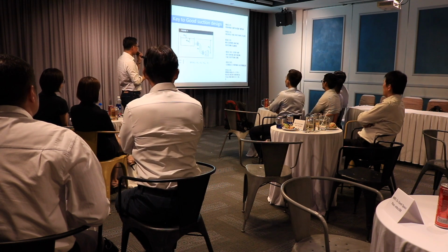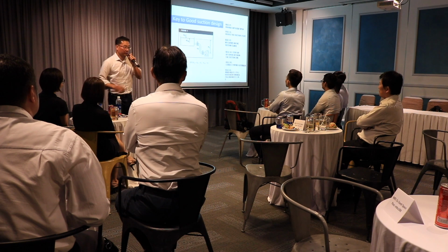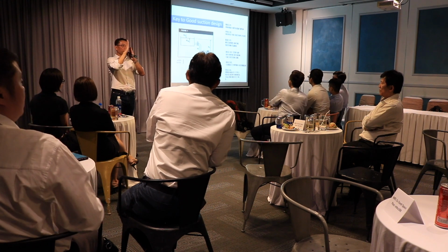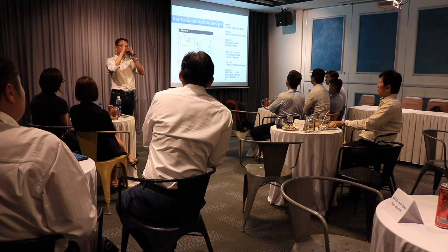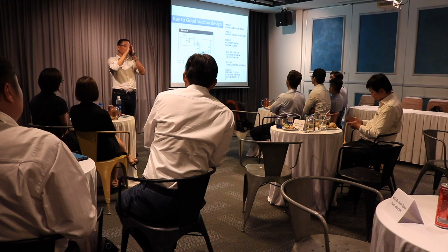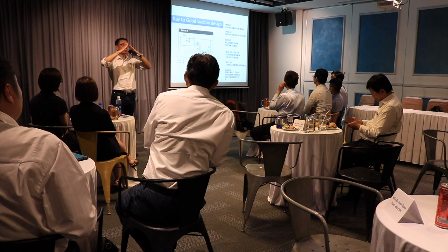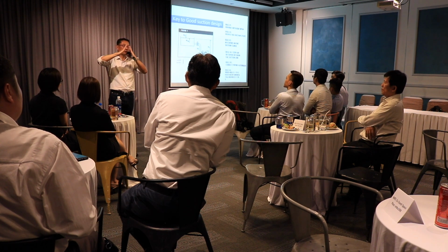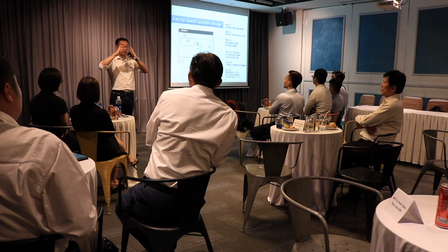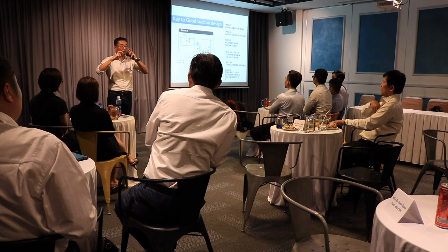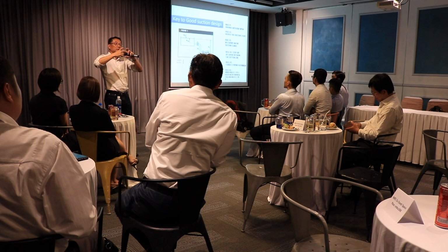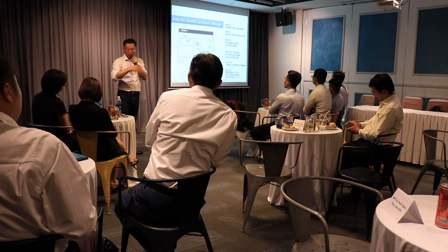Rule number 5, correct piping alignment. Now, piping alignment has angular displacement, which means the two faces are not straight. Sometimes the contractor comes and, because it's too low, they force the pipe. So this is to be prevented. Angular displacement means the flanges are not flush against each other. My pump is flat, but my flange coming is not flat. Torsional displacement: the 4 holes of my pump flange and the 4 holes of the flange on the pipe are at different angles. So this is what is meant by correct piping.